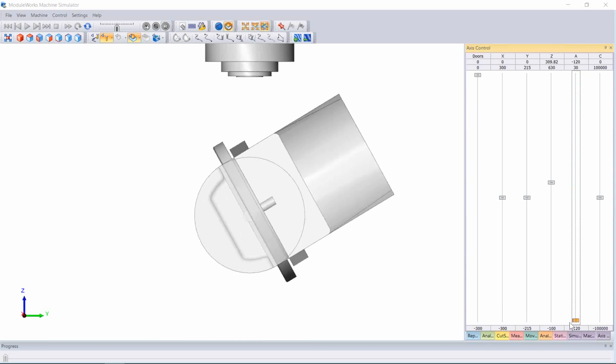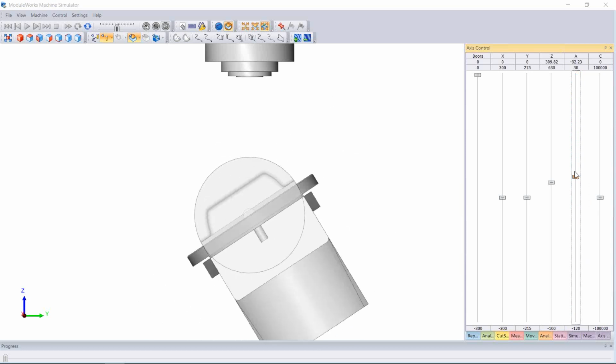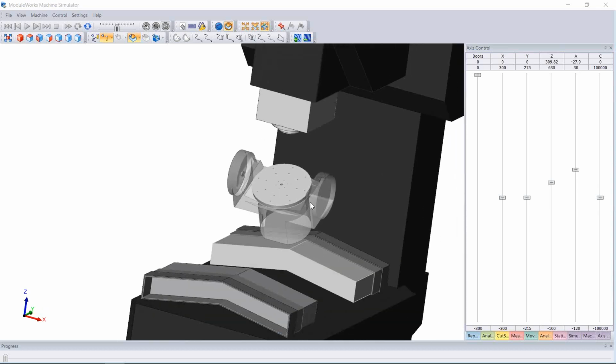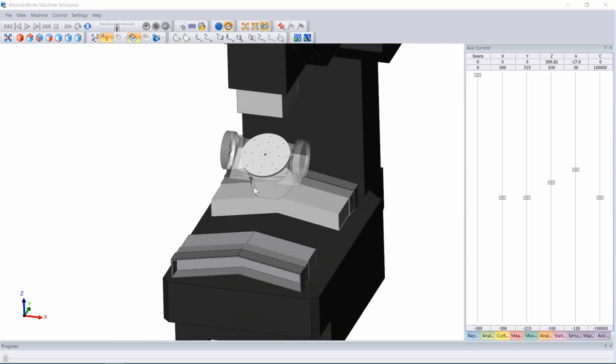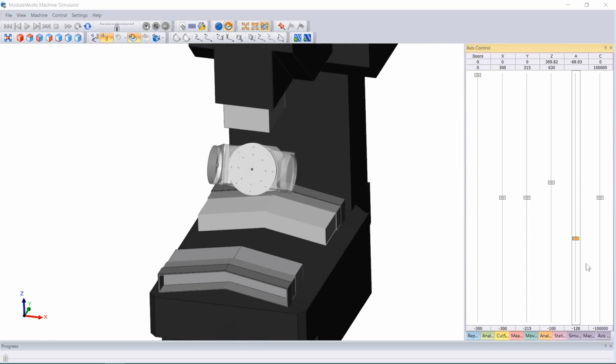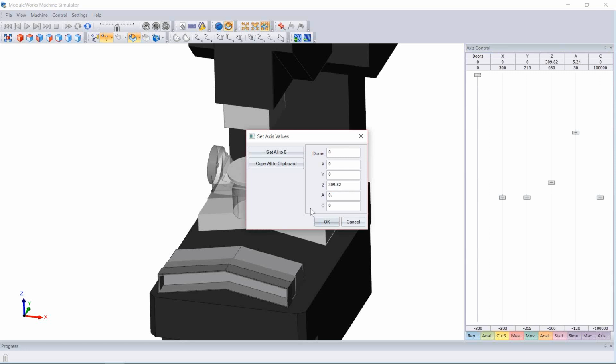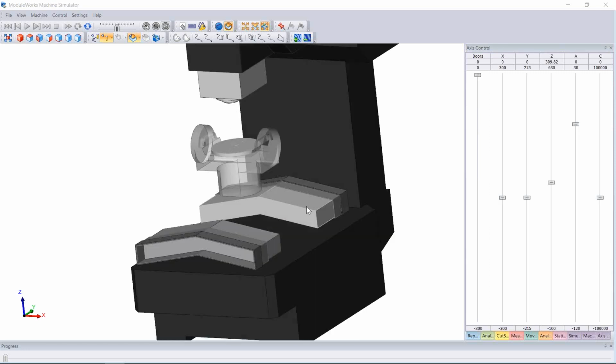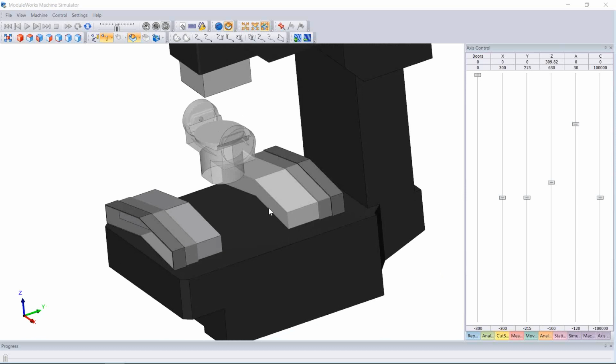And this really makes sense, because in most cases on 5-axis machines, you want to be sure that the operator can see what kind of operation is going on. In most cases, you'll never use another angle. At least you will try not to use it. But sometimes there is also a need for that. I'll explain that later. So this is why you have to use the negative value for the rotary axis. Now I also mentioned the y-axis negative value.